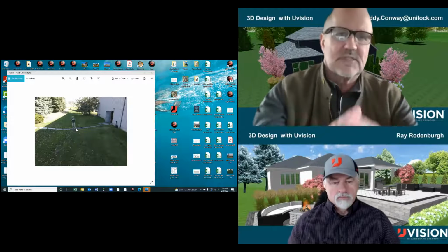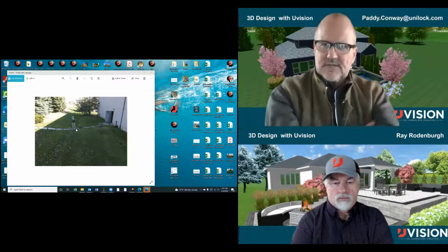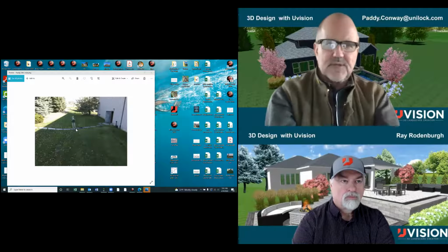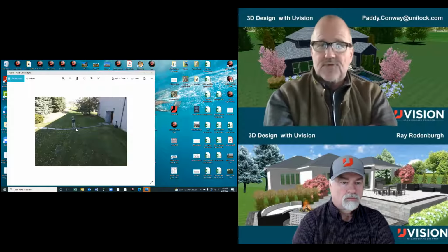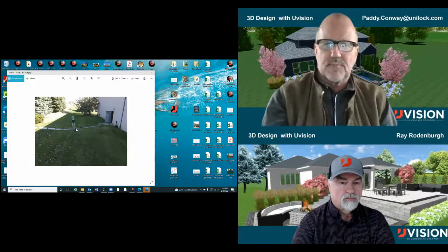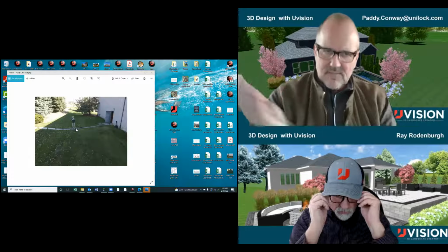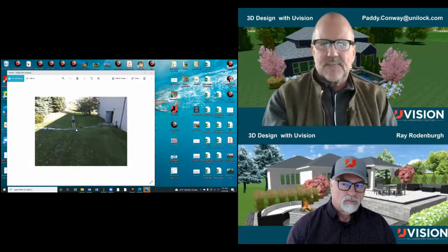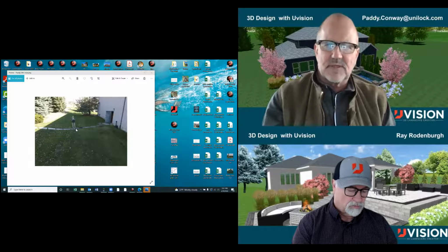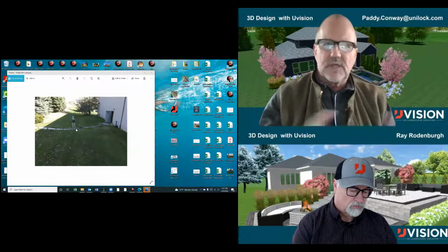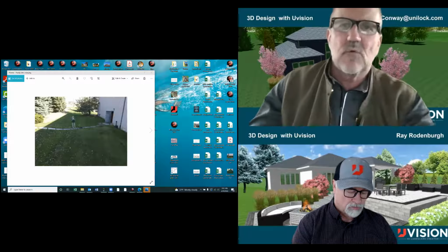I'm also going to discuss how I present it. If I'm on a project like this, I might tell my client, you might have a bid in here for like 28,000 and I might be 34, and I can address topics such as water buildup, putting in a swale, reswaling. Elevations tell us this. So it's not a flippant bid by just looking at a 2D plan, measuring by the square foot and pricing by the square foot. It's an in-depth analysis of what soil does to our bid. So we'll come back to that.